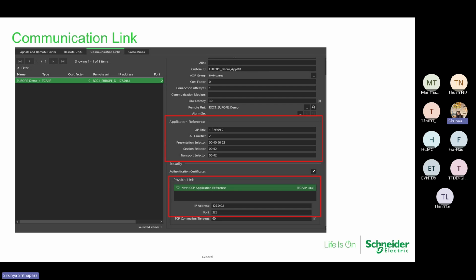In the feeder, do you have it? In potential, yes, for example the reclosers or whatever is in the middle of the feeder. I haven't decided yet, but maybe we will collect all of those data signals and send them to you by ICCP, maybe for all. Or if you need, we can separate those communications: maybe ICCP 1, ICCP 2, or maybe we can use IEC 104 for every device if you want.